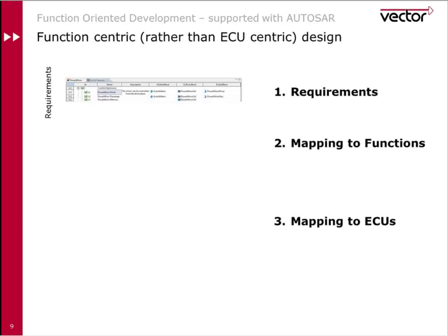This potentially means adding more sensors and yet another ECU into the vehicle. But we have many, many ECUs in the vehicle already, perhaps 100 or more ECUs. And there are ECUs everywhere within the vehicle, in the roof, in the floor space, in the doors. So adding a new ECU means more weight, more wiring harness, more load on the bus, and it's additional cost that the OEM wants to minimize.